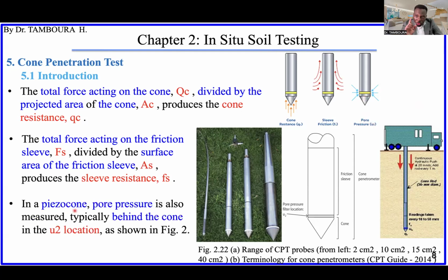In the piezocone only, I gave you the definition of the piezocone in the previous slide, the pore pressure is also measured, typically behind the cone, u2.